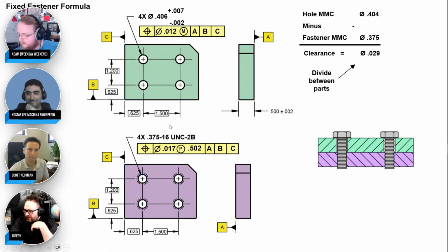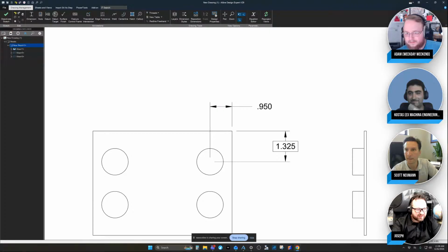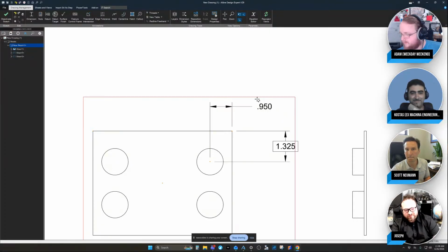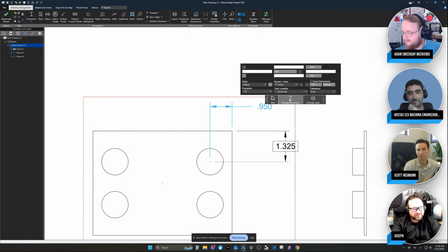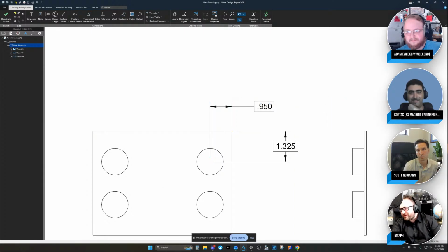We had a quick Libre question come in. It was asked, can we do basic dimensions in Libre? Adam answered that really well, but I'll just say you click change dimension, tolerance, and basic. Can you mass change them all at once, or do you have to do them one at a time? You could change the standard for the file. You can actually.